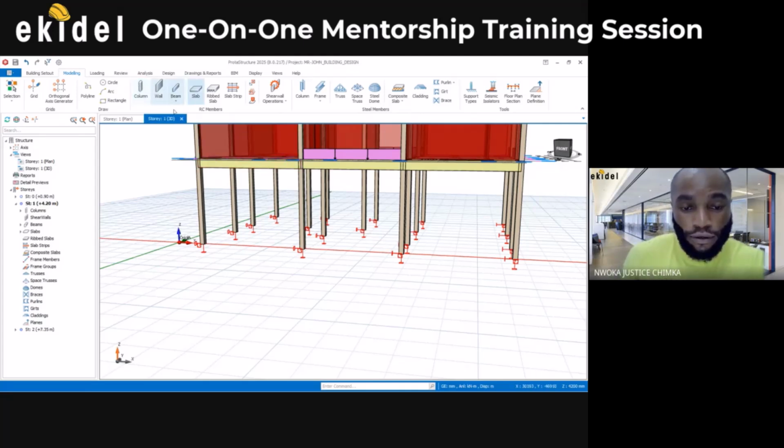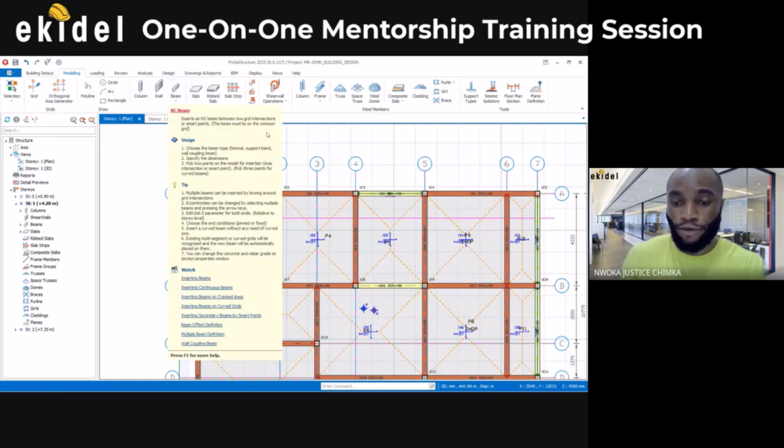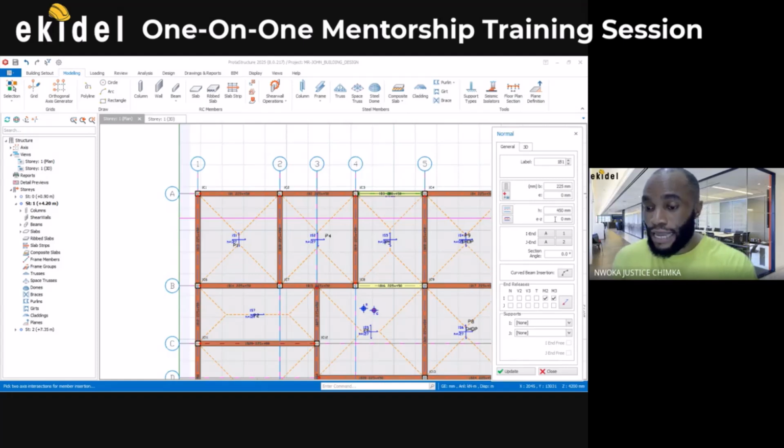So okay, I'll come back to my plan view here now. Click on my beam, then click on normal beam. Then on this, I can choose to use the same section. Let's use the same. Then I'll come to my 3D. You can see the 3D tab here, it's showing the 3D model. I'll click on this now.